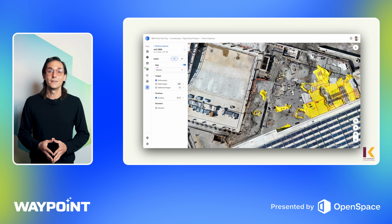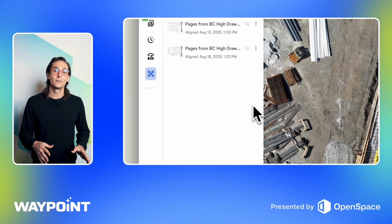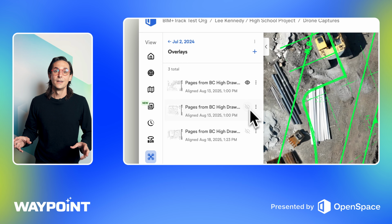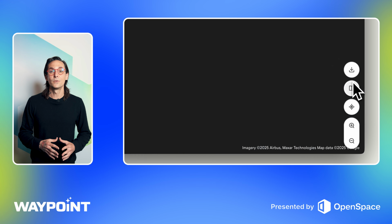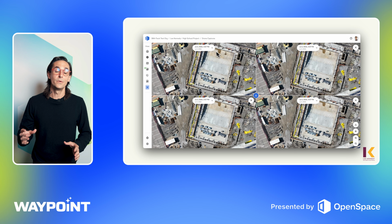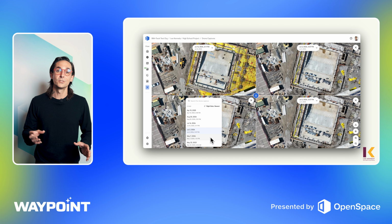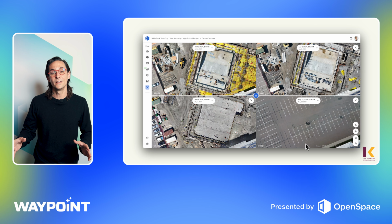With OpenSpace Air, we make it easy to upload images from any drone. Your teams don't need to change their workflows in the field, and we automatically generate orthomosaics, meshes, point clouds, and elevation models. And then you can bring your drawings and site plans and overlay them onto the orthomosaic. This opens up opportunities to start understanding the site before you've even won the bid. You can plan the first phase of work where materials are going to be delivered. You can manage QA, QC, and earthworks with overlays.